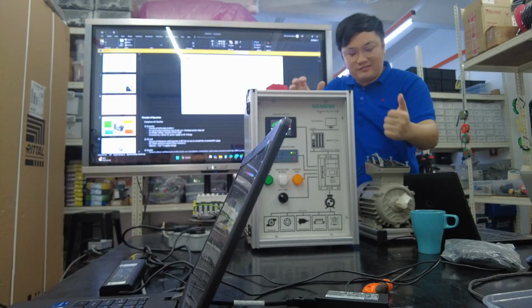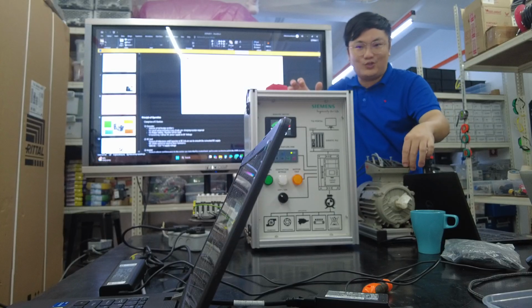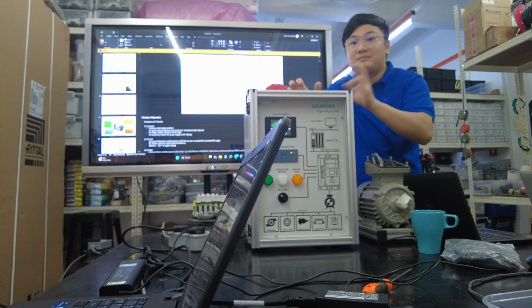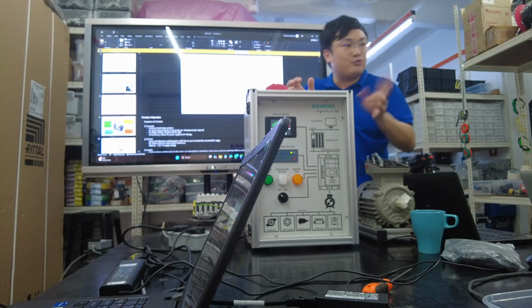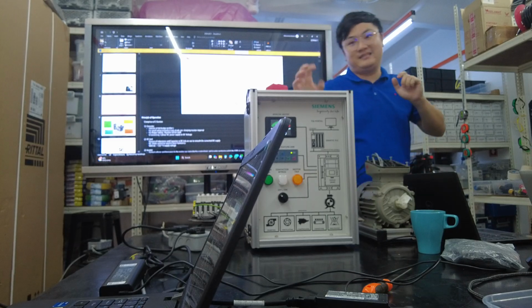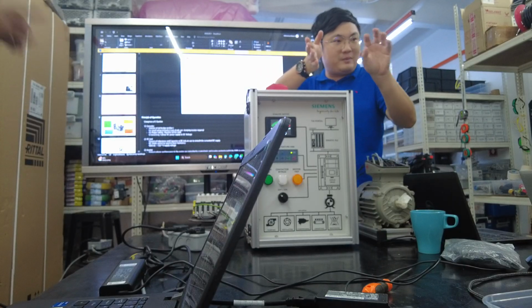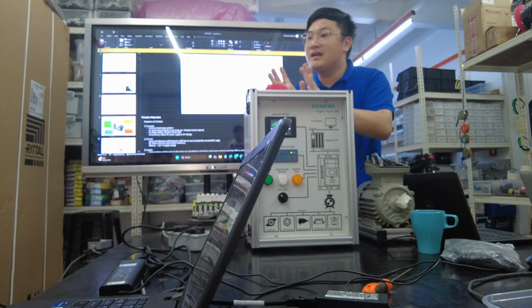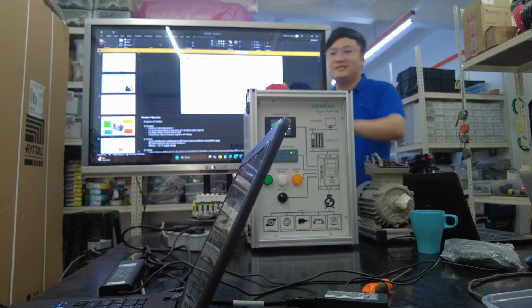Okay? When you talk about DOL, what is the power factor? When you're running a motor, efficiency depends on the IE class. Efficiency is usually about 89%, or maybe sometimes 85%. For IE2 the minimum is about 90, IE3 up to 95, IE4 98%. So when you draw 10 amps, about 10% of the energy will be converted into heat and vibration, all those things. There is wasted energy. With an inverter, usually there is no wasted energy.